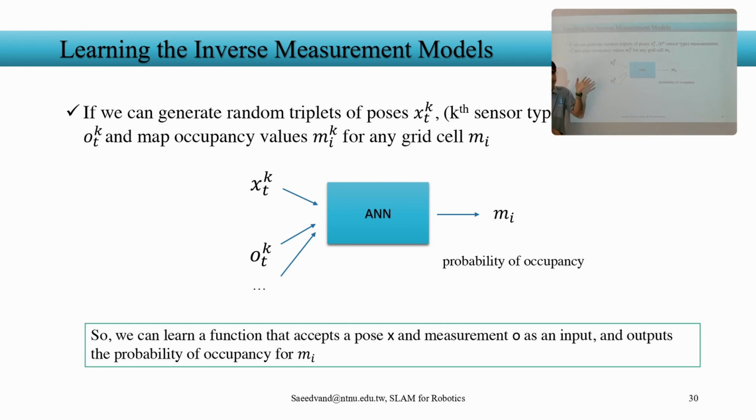If you have a robot, right, and the robot has 2 types of sensor, and you train a neural network based on thousands of times of trying, the error on the observations is static in the sensor model that you have. So it's not going to change too much. Your LiDAR has some predefined error. Your camera detection, the RGBD, has some error, right?